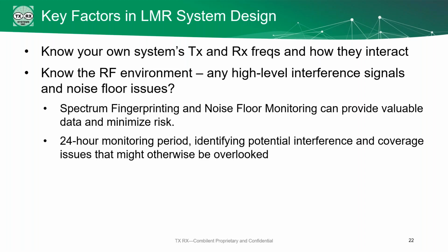To help with this, though, TXRX offers spectrum fingerprinting and noise floor monitoring as a service. This is a 24-hour monitoring period where we will come to your site, set up some monitoring equipment, and listen to what's going on in the environment for a full 24 hours. At the end of that time, you'll get a report saying what high-level carriers are in your area, what you need to isolate for, whether or not you can just use a basic windowed system or if you need something a little bit more complex.